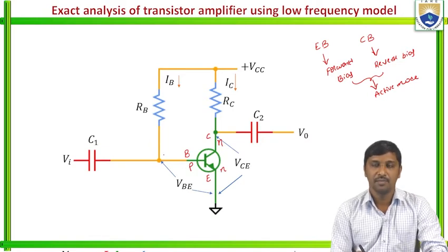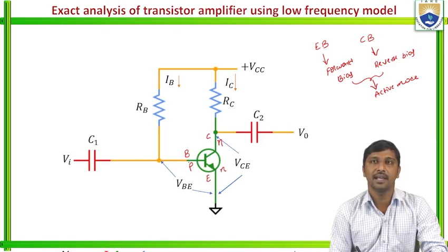Base is made with P-type material. Hence, this base material is biased with the positive pole of the DC source through a biasing resistance, that is the base resistance, represented as RB. From this biasing, the input junction, or emitter base junction, acts as forward bias. Similarly, we need to bias the collector base junction as reverse bias.